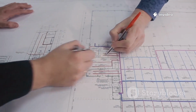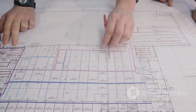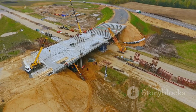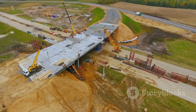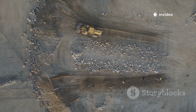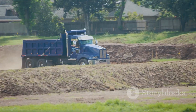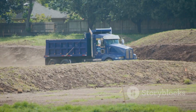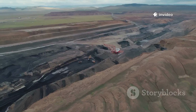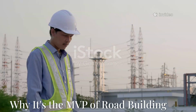Reading the diagram, you can see exactly where cuts and fills happen, and how much dirt is needed or available at each point. The mass haul diagram turns a chaotic earth-moving project into a clear, manageable plan. It's the difference between organized chaos and total confusion. In road building, every truckload costs money, so organized chaos is the only way to survive. This simple graph is the key to making sense of millions of cubic yards of earth, and it's the first step to building a road that actually works.